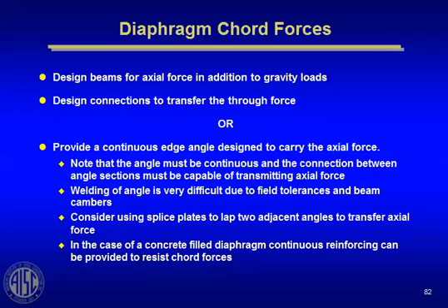Okay, we're going to talk about the diaphragm chord forces. Just like any beam, when you flex it, you create tension in one flange and compression in the other flange. In a diaphragm, those are called the chord forces. You have to design your diaphragm for those. How do you do that? You either put an edge angle on there and design the edge angle as continuous at the edge of the diaphragm to collect that chord force,